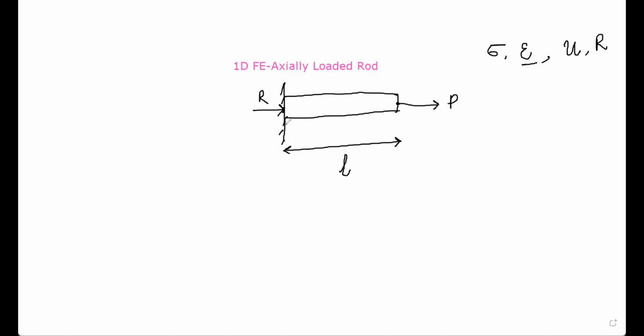Apart from this load P, let us also assume that this rod is subjected to surface tractions, and the traction T is a function of X. The step number one in finite element formulation is often stated as dividing the problem into finite elements, small elements.